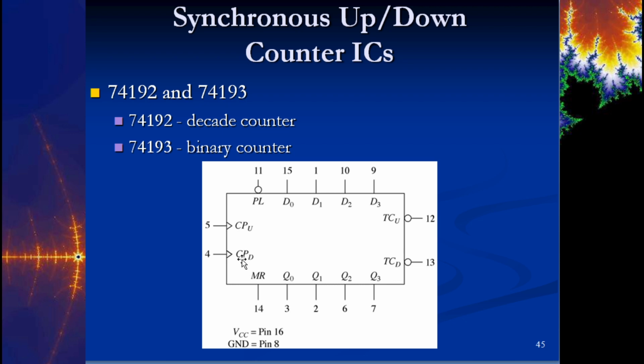So it still holds that if you take the output Q, and we look at each output Q out of the flip-flop, okay? If we wanted to create a manual down counter, then we would have to either have a chip that has a Q not output, or take the Q and run it through a not gate. If you remember, that's how we do a down counter with the ripple counters.